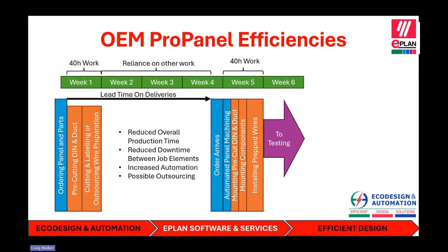And then mounting your components on, which I've got at about the same time because that's just a process, and then followed by installing prepared wires. So using a wire guide, you can put the wires straight into the panel, and there is, of course, the smart production, which can show you where to terminate it to and from.